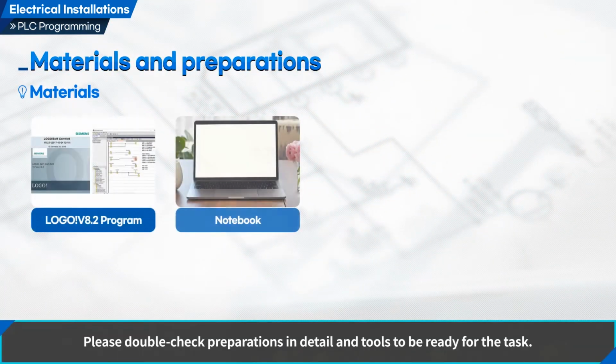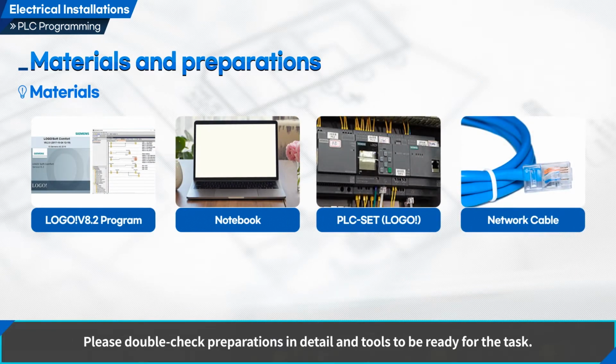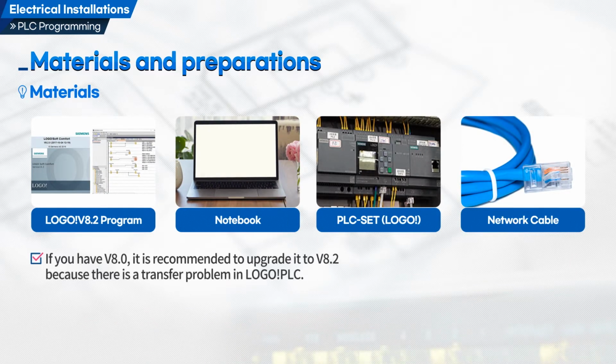Please double-check in detail and get the tools ready for the task. If you have V8.0, it is recommended to upgrade to V8.2 because there is a transfer problem in Logo PLC. Laptops must have LAN ports configured.